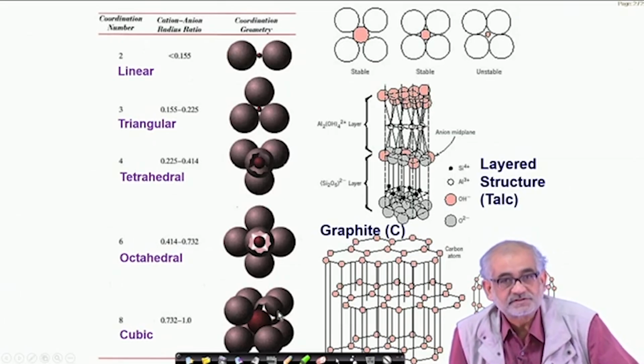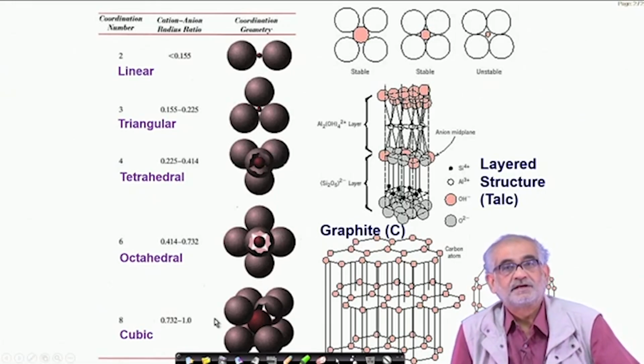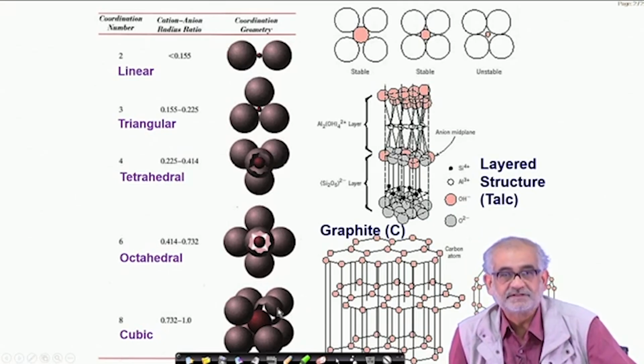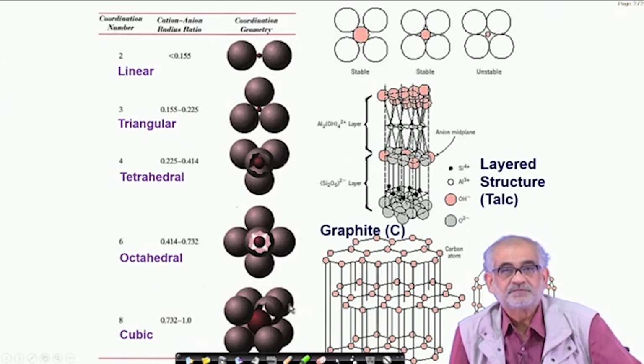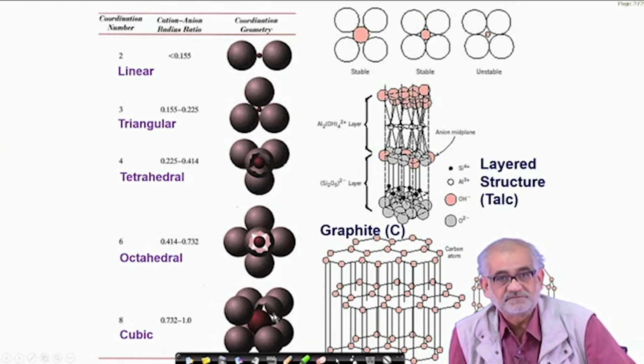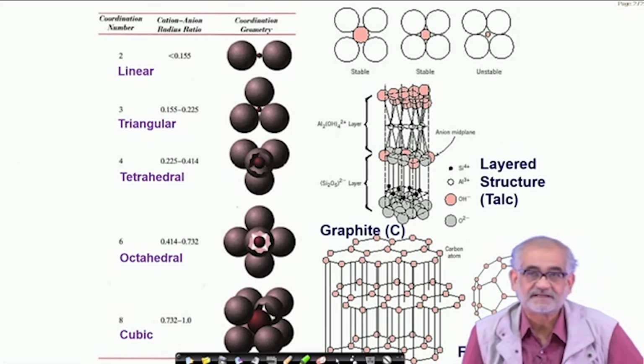And the most efficient packing, which I already mentioned, is manifested in the form of face-centered cubic and hexagonal close packed. They are possible only when you have similar sizes. So this is going to be possible only for elemental crystals of only one single size of species, and the maximum possible size difference there is basically none; they are of the same size, so the ratio is 1, and only in that situation can we have the largest packing density.